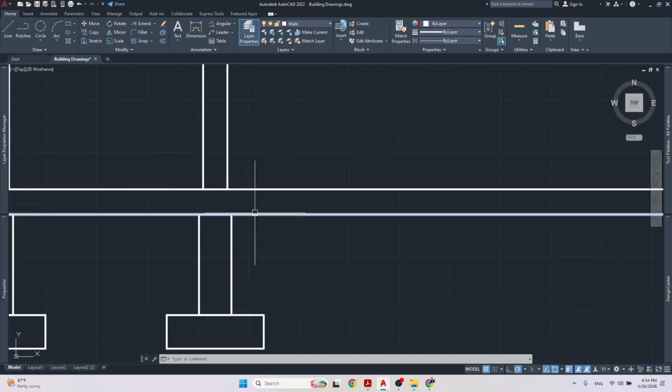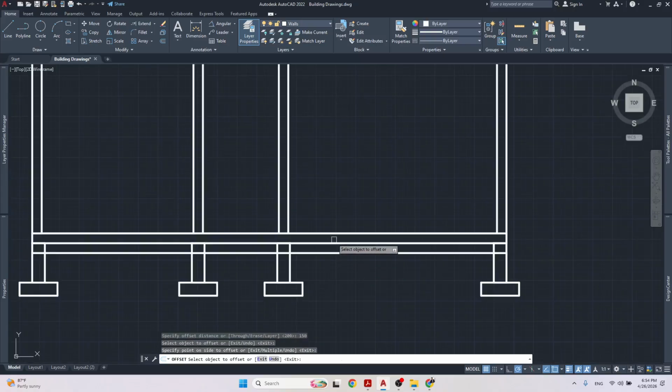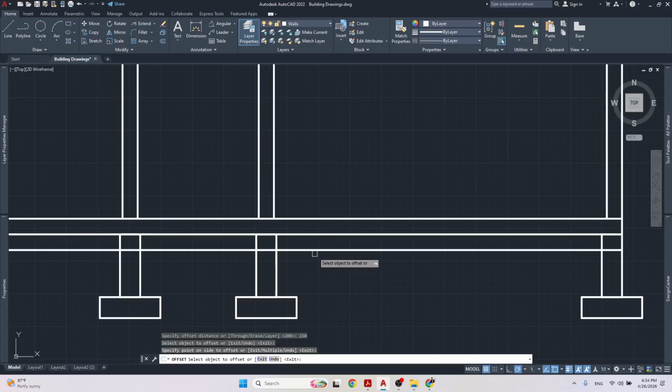So underneath, in these two lines, we have the finish floor, then we have the concrete slab, and then we have the sand blinding layer and the damp proof core, and then underneath of that we have 6 inches of hard core. So offset come down, that's 6 inches of hard core, and then underneath of that now we'll have earth.